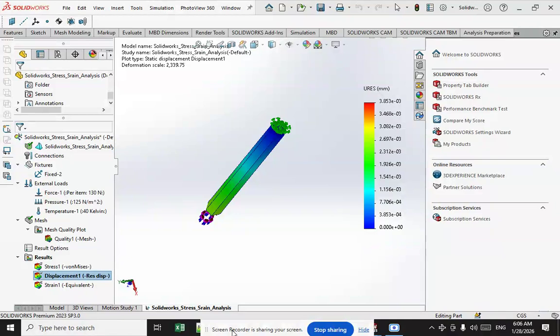For more complex structures, more complex methods such as theoretical solid mechanics or numerical methods may be required. Numerical methods include the direct stiffness method, which is also referred to as the finite element method. The object is to determine the critical stresses in each part and compare them to the strength of the material.